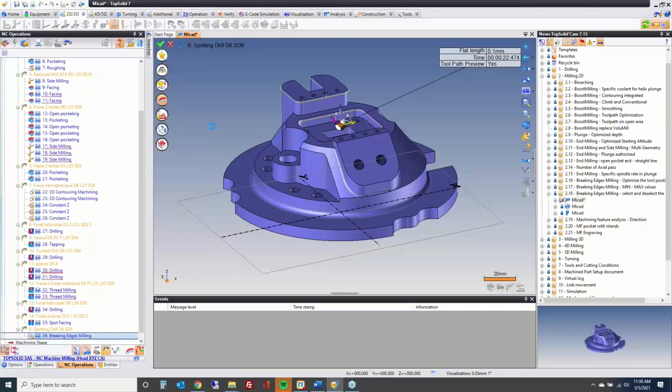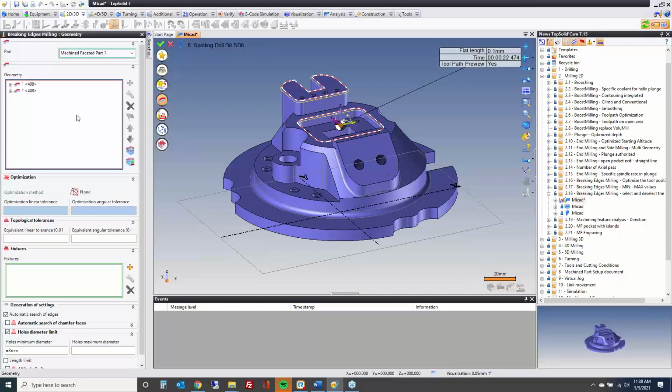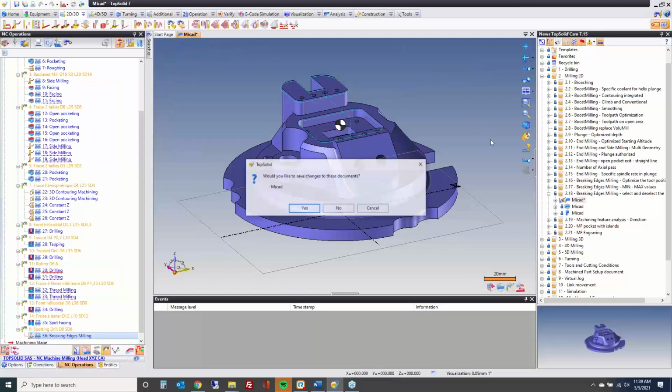we go to geometry, and I just have 2 selected right now. Some automation was done to select these things, right? But maybe I decide I don't want that one anymore. We leave behind as a yellow curve the automatic profile that was found in the background. Okay? So this way, if you wanted to put it back, you can easily select it. It doesn't disappear. You don't have to rerun the search. Okay? So it's just a way to help you organize and select, deselect things dynamically. Perfect.